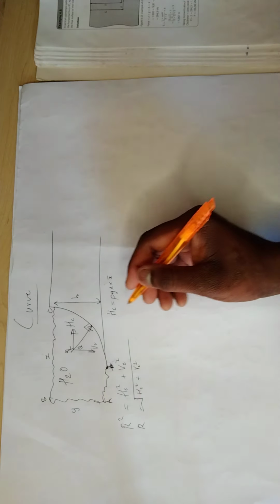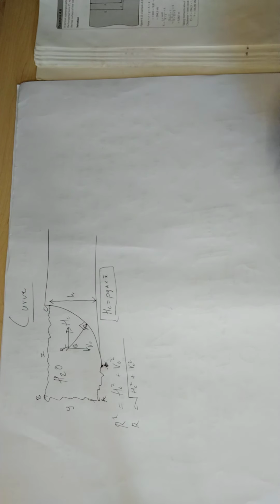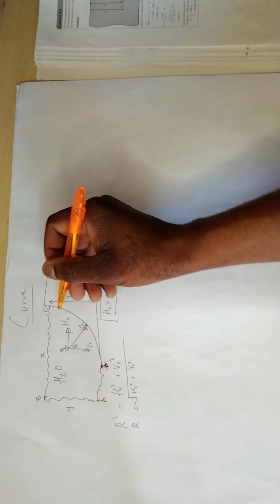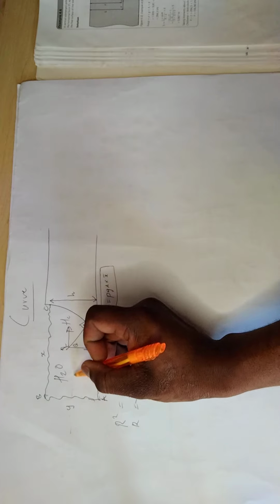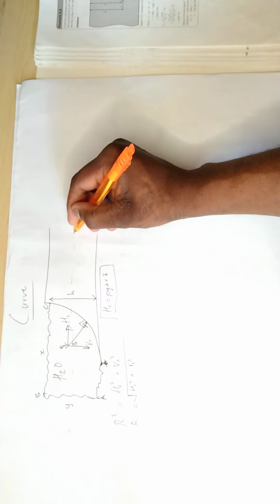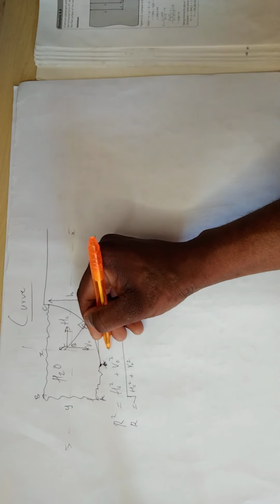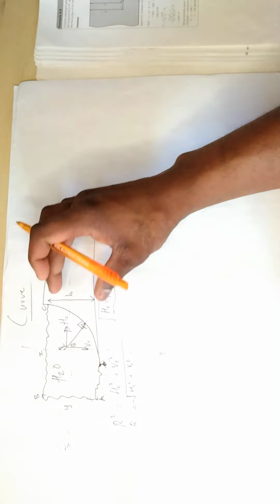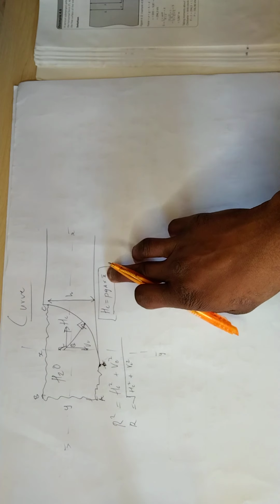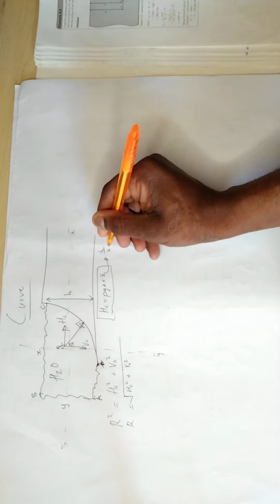So this is the first formula to look at. What is the X bar? I told you, it acts on the middle of the area. This here is going to be our X bar, and here is going to be our Y bar, right? You see it? So we have to find half of our height to get the X bar, remember? So in order to get this, it is height over 2.